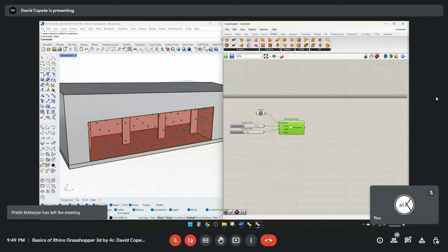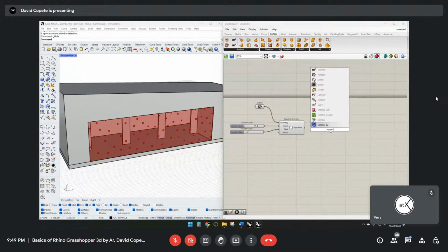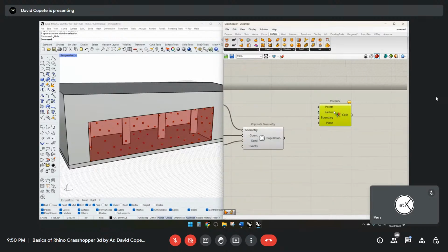Now we'll take these points that are randomly set on the surface. We're going to go to a Voronoi, and we're going to use this one. Now there are other Voronoi components that are useful in other cases. We'll be using this one. Now the points, well, when we see this component, it doesn't work because it needs some inputs. It needs some points, which will be this, a radius that can change the pattern, but the most important thing is going to be the points.